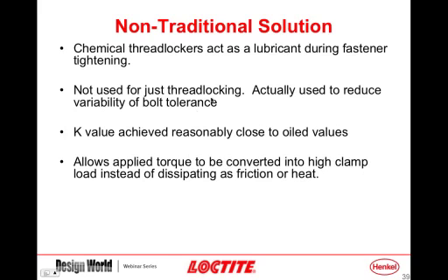In the testing that we were doing, we were finding that using a liquid thread locking does seem to bring more consistency to the system, that the applied torque is going to generate clamp load, and you get more consistency across different manufacturers' fasteners, as well as a more consistent clamp load as an as-received fastener, which was shown in that second study.